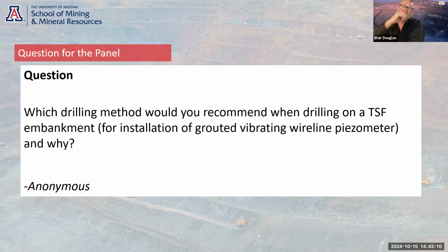So I was just going to say we do a lot of work on tailings dams, so the heightened anxiety across the world at the moment. I've never really come across that argument about injecting too much water into the formation or fluids. I know it's there, but the reality is, you've got to put a fair bit of pressure in the system to make it fail. If the introduction of drilling mud does that, then you've got serious issues. So I'm assuming you're on a facility where you're trying to understand, and you're putting vibrating wires in to get some monitoring in there, so you can maybe set some TARPs, trigger action response plans.